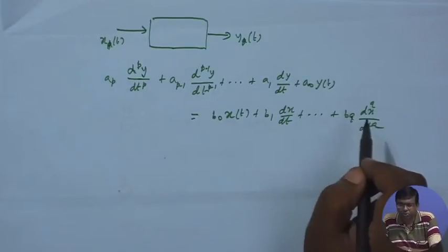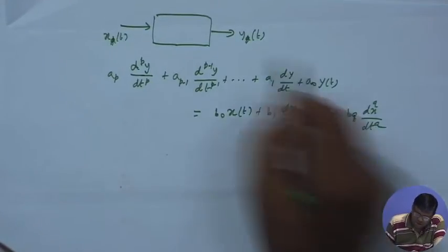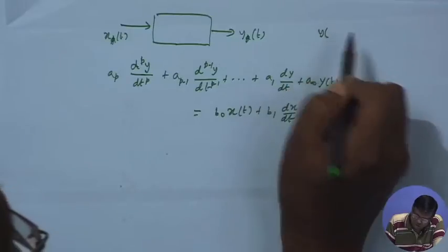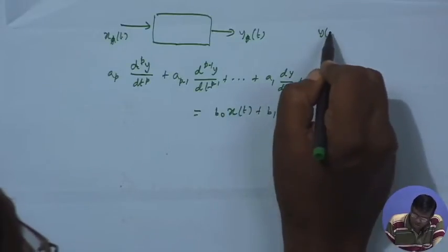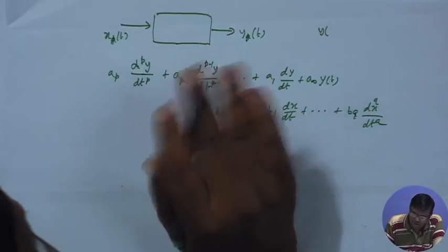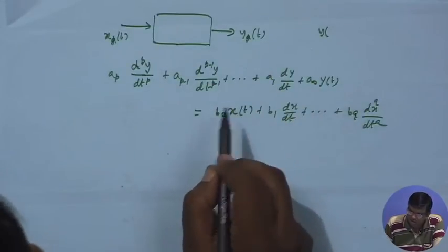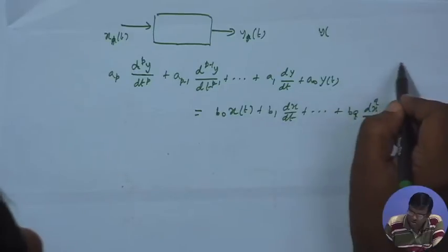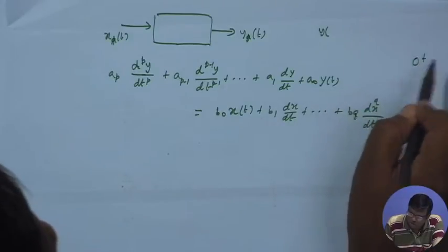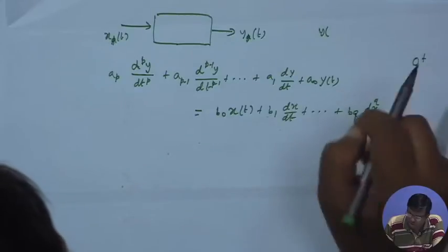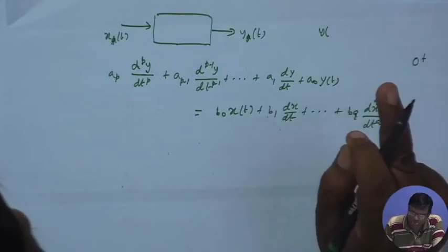This equation will have two solutions. In fact, this equation is given and you need initial conditions. These initial conditions are given, that is, the system is switched on at t equal to 0. Input is 0 at t equal to 0, input starts its value from 0 plus. So, at 0 minus, at the point of switching on, input is 0 and then it picks up.